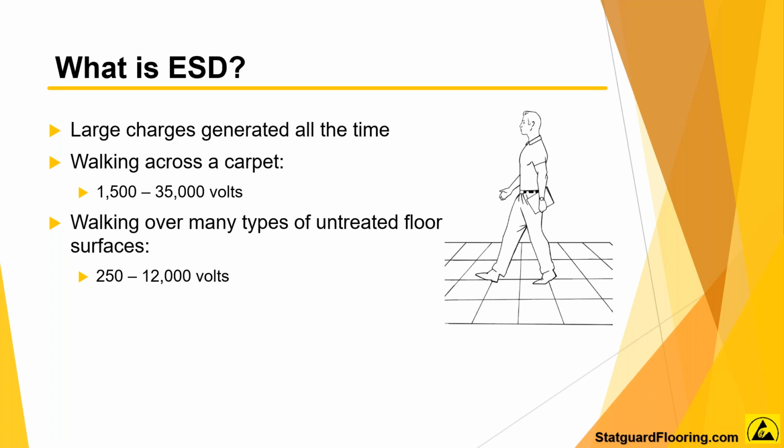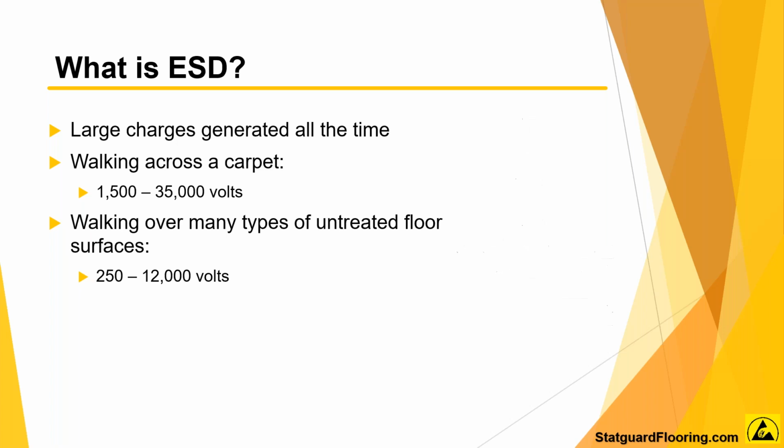So how do we control electrostatic discharge? Per ANSI S20.20, all conductors in the environment, including personnel, shall be bonded or electrically connected and attached to a known ground. Electrostatic protection can be maintained at a potential above a 0 voltage ground potential as long as all the items in the system are at the same ground potential.